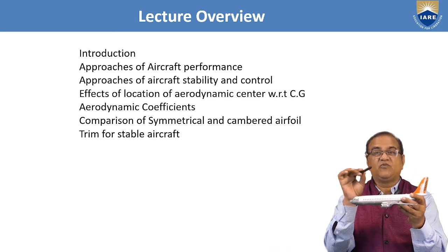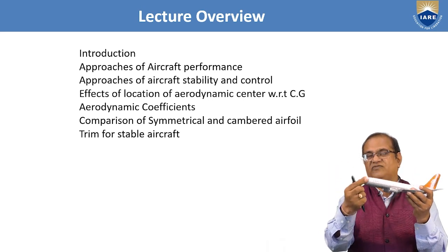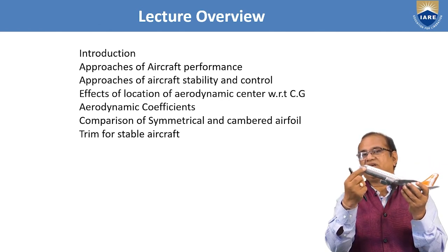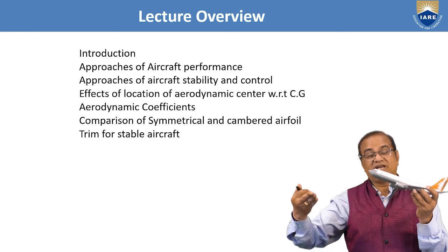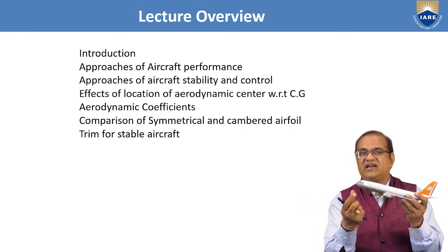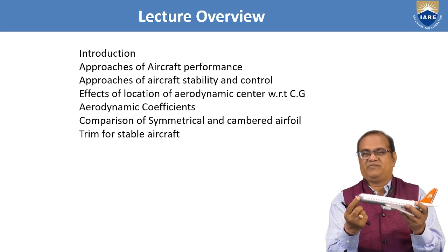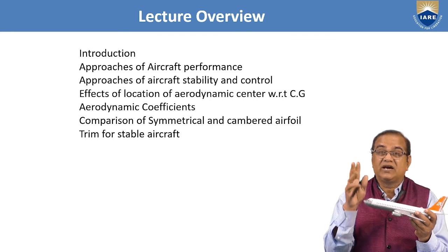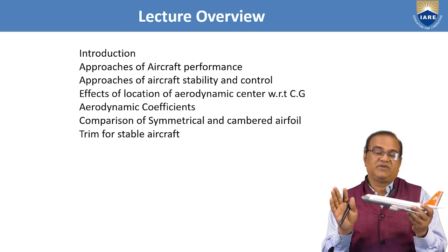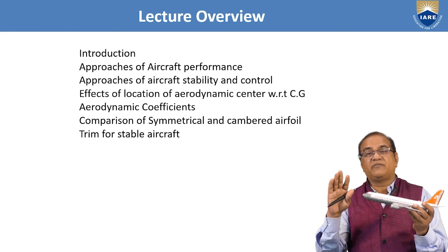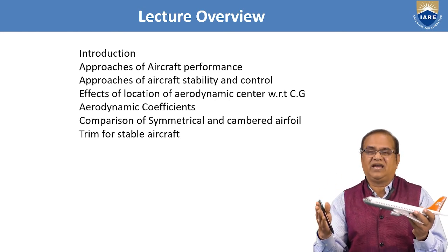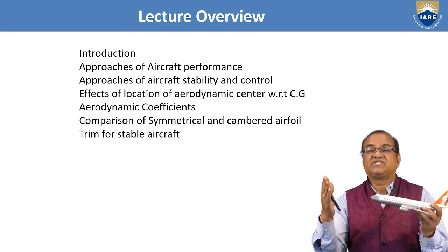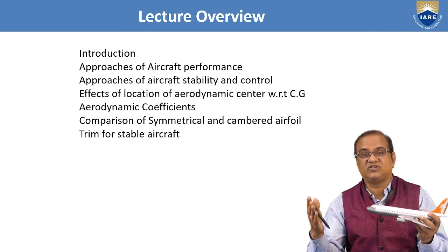So in this case, we should make sure that the tendency of the nose is to come down. It should not go up if the angle of attack is increased. On increase of angle of attack, the nose should go down, not up. If the tendency is like this, the aircraft is longitudinally statically stable. But this condition alone will not solve the problem, because we want to fly the aircraft also, and flying is only possible with a positive angle of attack. So the trim condition should also fall at Cm naught greater than 0.